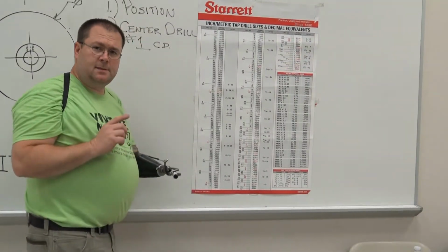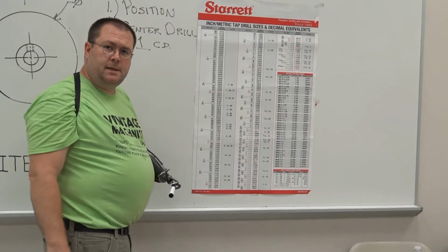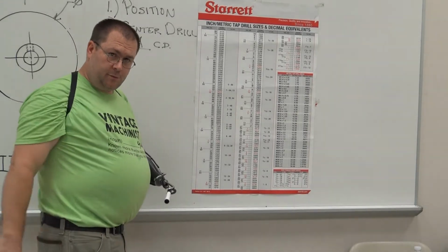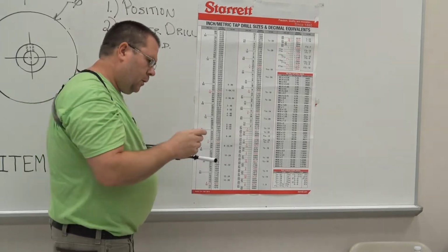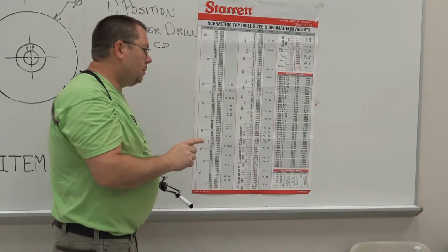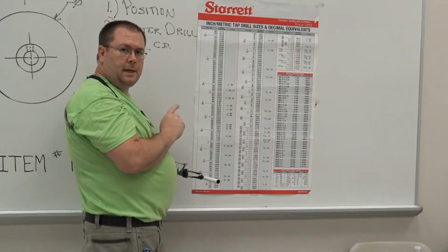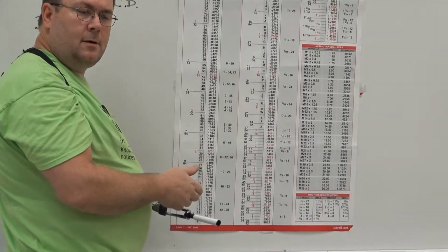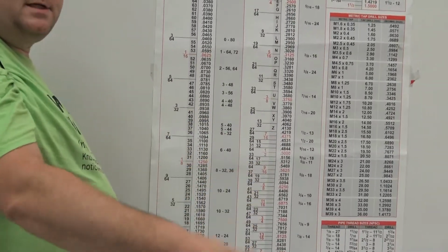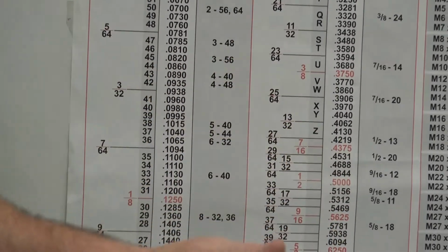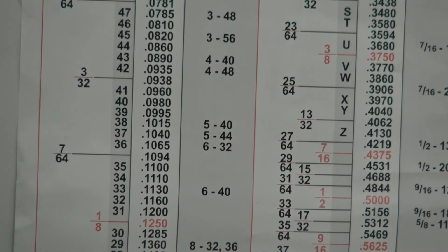So now we're ready to select our drill size for that 6-32 Unified National Coarse thread, okay? We've already stated that we care about the minor diameter, so we're going to pick out our tap drill size. In industry, we call it the tap drill size, okay? You should get used to hearing that. If you go into a machine shop, you need a tap drill for a 6-32.